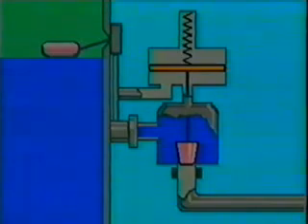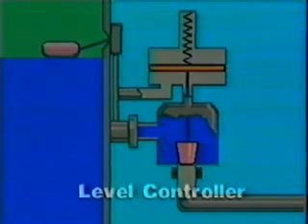Glycol level control on the contactor is important in stabilizing unit operation. The level controller should be adjusted to hold a uniform flow rate of glycol out of the contactor. It is more important to hold a constant flow of glycol out and let the glycol level in the contactor vary a few inches than to hold a constant level in the contactor and let the flow out fluctuate. Flow rate surges leaving the contactor will cause the reboiler to operate inefficiently and may overload it.